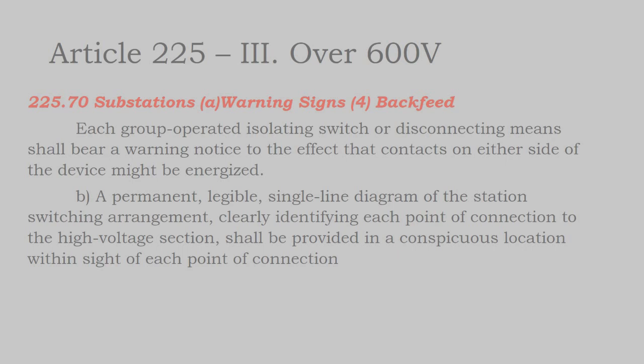And when you get into, say, commercial design, you might think, well, what are all the signage requirements that I'm going to have to get into? Here you see a callout that says for substations, which are higher voltage systems, I need to have a plaque with a single line diagram identifying the points of interconnection. And it's not uncommon on commercial inverters that are going from the 600 volts of the array into the 480 volts of the utility primary to put a single line diagram around the inverters as well.